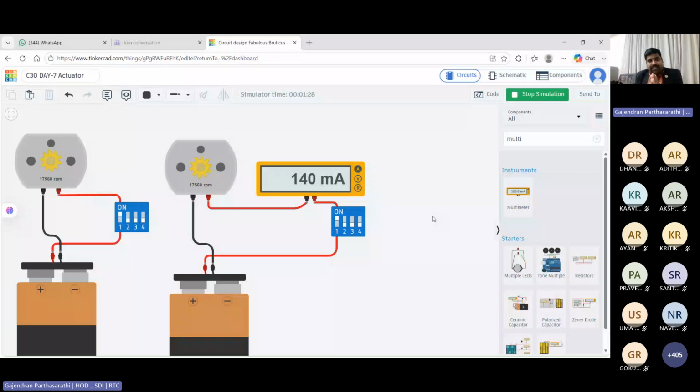So now what we did is the motor on and off condition, and we measured the current. The conclusion, please take down: our Arduino Uno board, the individual port can deliver a maximum of 20 milliampere only. Now you tell me, if Arduino can deliver only 20 milliampere, then how can I drive this DC motor? Anyone please tell me what I want to do? Any idea?